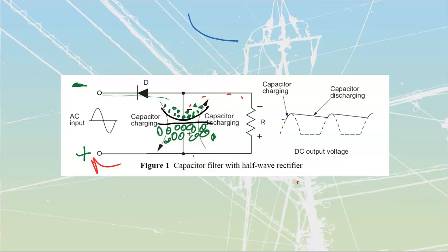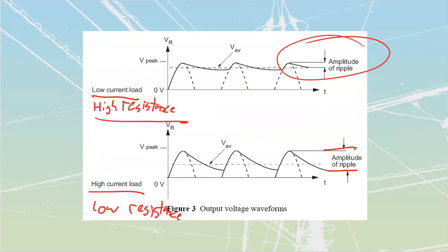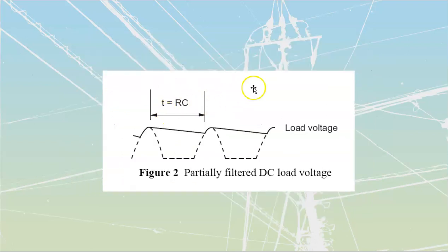The problem with the bigger cap is that we get massive amounts of inrush during that charging, and it can sometimes be enough that it's going to trip out some of my load protection over here. The other drawing that was previous to this one over here, that had tau equal to RC, is a little bit of a difficult drawing to understand.